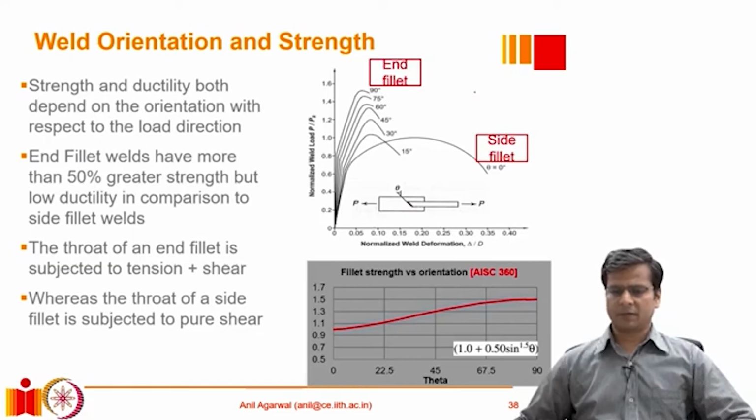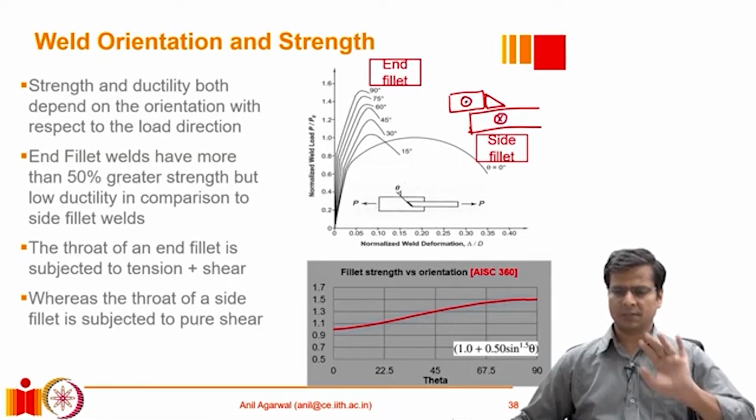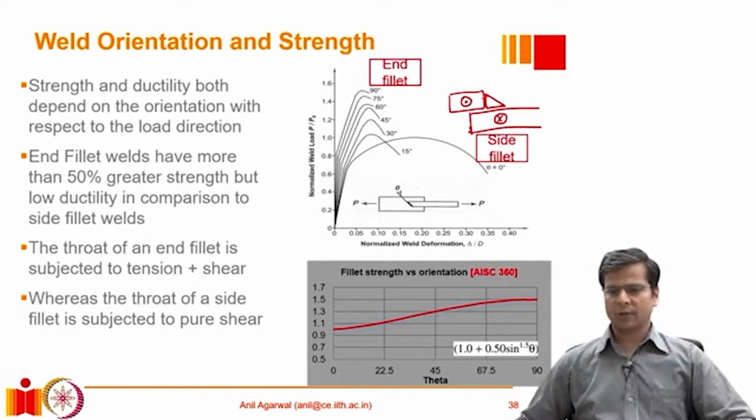So let's say I give you a scenario where there is a plate and there is another plate right under it. The two plates are welded together using a fillet weld, and imagine that everything is symmetric and so on, so that there is no movement introduced. Now what we do is we pull this plate outward while we push this plate into the screen, into the board. Now what do you expect the stress state in that fillet would be? In this situation, the stress state is relatively simpler. There is a shear at this interface and also there is a shear at this interface. So this situation is very different from what I had just discussed before.